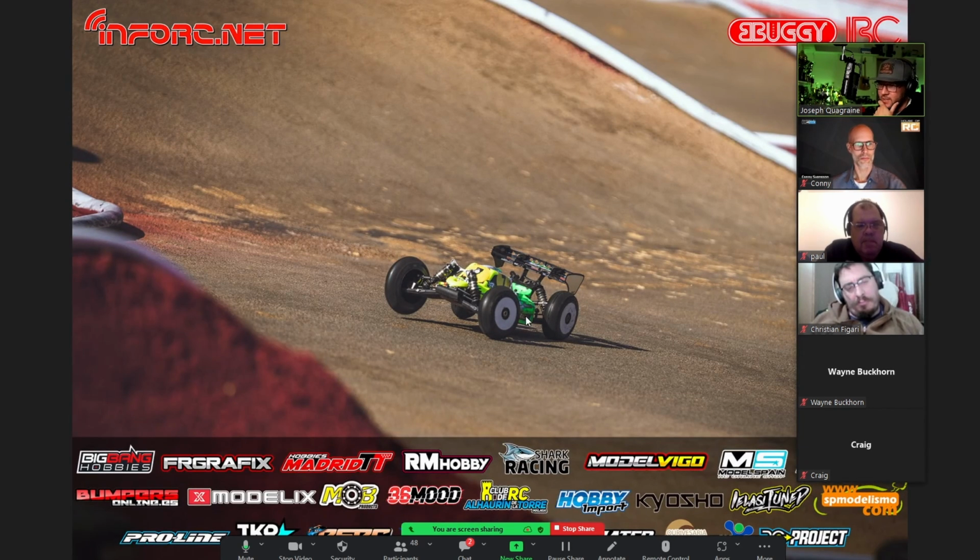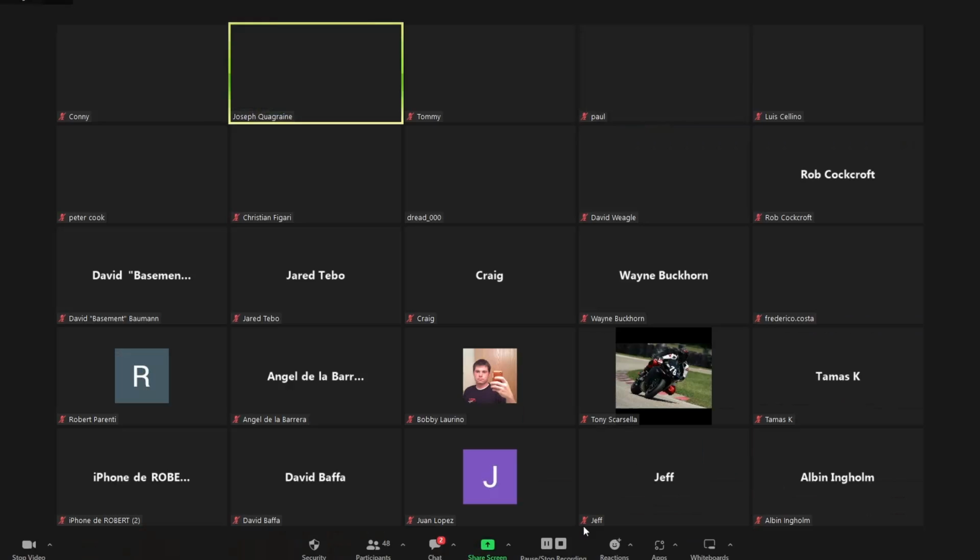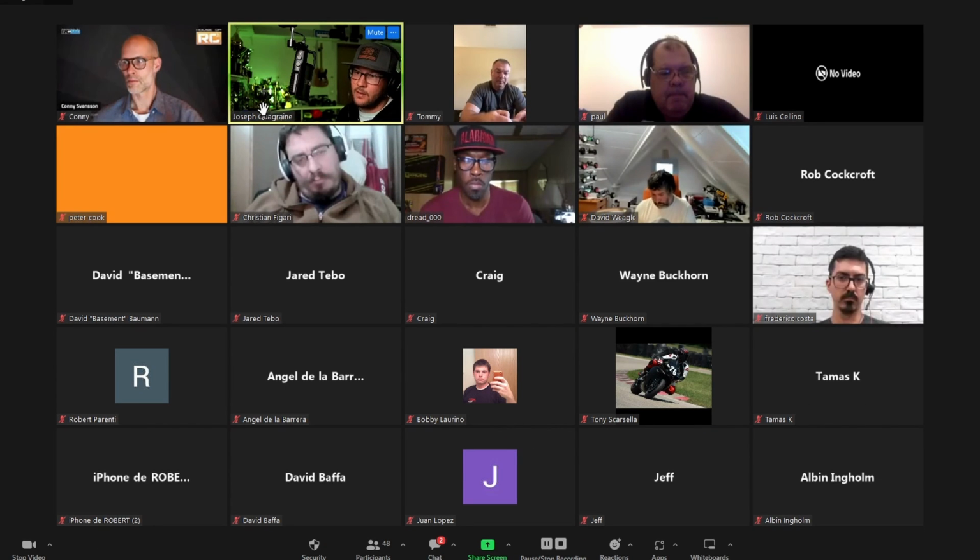This is another example accelerating. This car is outside the working range. It has heavily rolled onto the outside rear tire, front tires, inside tire is off the track, outside practically off the track too. So this is a car that's not performing at its best. So clearly, the working range is a thing we need to keep in mind.